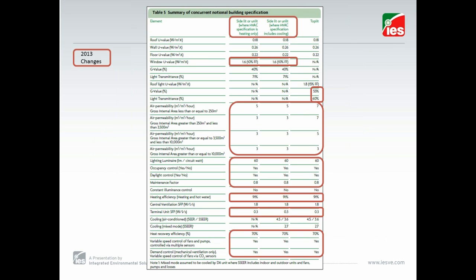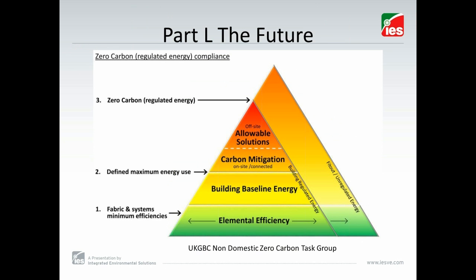Commercial offices and other building types will require significant improvement in lighting efficiency with increased use of daylight, therefore more use of dimming and or new lamp technologies. And be careful in the selection of your systems, because auxiliary energy is a significant proportion of the energy consumption. So you've got to consider the trade-offs between increasing fan energy as well as reducing cooling loads.